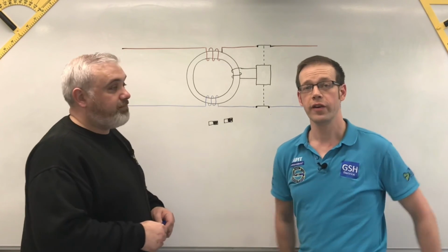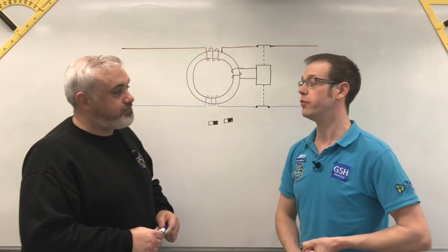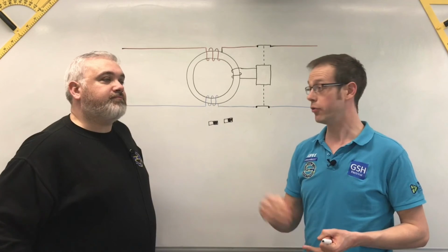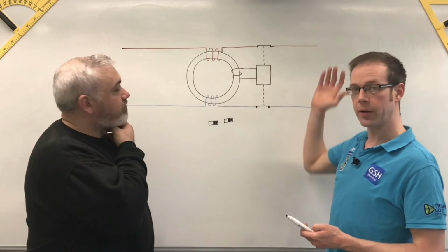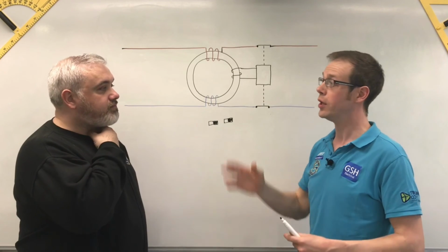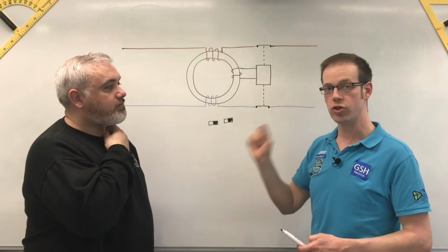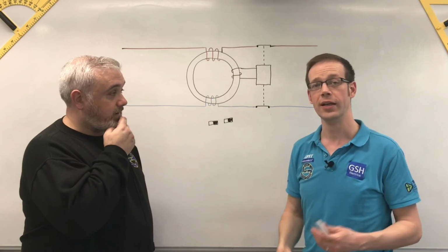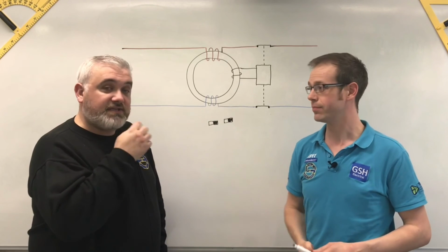Absolutely. So hopefully we can see from the information that we've watched in this video that if you have the types of load which are becoming increasingly common that feed DC back into an AC circuit, either under their normal operation or even worse when they've gone faulty, and then a typical domestic fault occurs where line and neutral or neutral and CPC come into contact with each other, or worse still, somebody gets a shock, then the RCD is not going to trip when just 30 milliamps flows through a person. Now, if we get more than 30 milliamps flowing through a person, that is a serious problem because it goes above the level where someone can die. And this is fault conditions, guys.